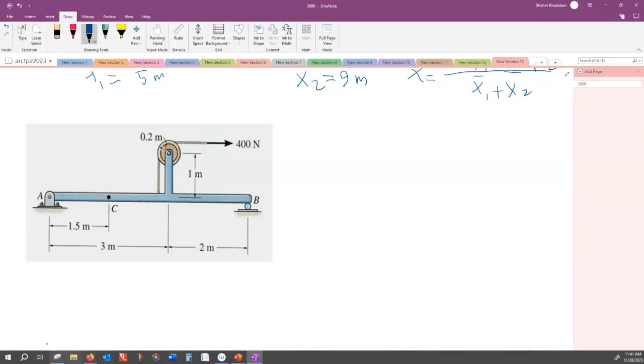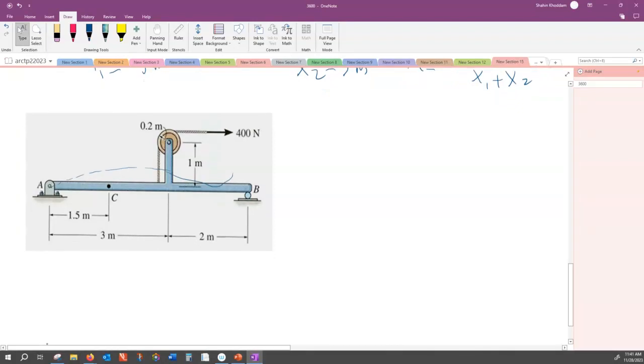So I can imagine if these two ends are fixed here, and then I pull that part up, it's going to go through a different, but definitely the radius of curvature will have changed, right? Everyone can visualize it. So therefore, your first conclusion is this is a beam, it's not a bar. Okay, second.